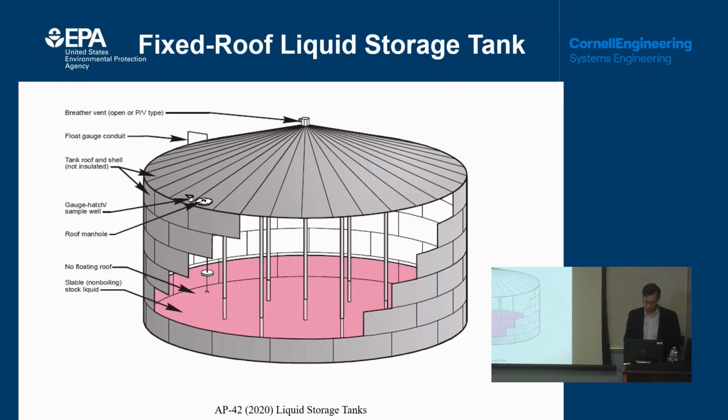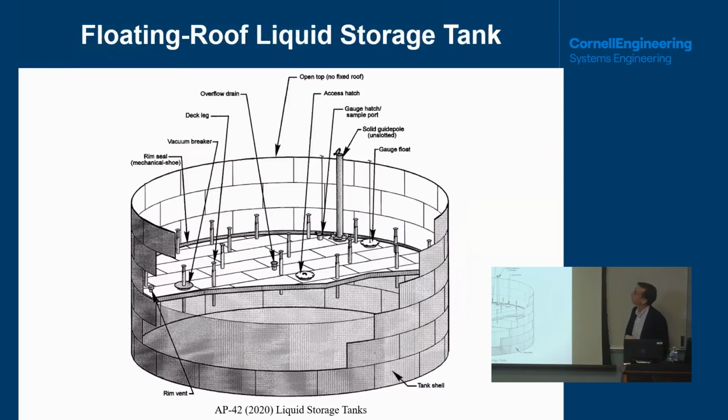So what some people do is they put a floating roof on top of the stored material, like gasoline. So this roof is sitting right on the gasoline, and the roof moves up and down with the material, right? You pump something in, the roof moves up, you pull the material out, and the roof sinks. When the roof sinks, you can imagine that the sides of the walls are still going to have liquid on them, because you dropped this floating roof down. And so that material evaporates.